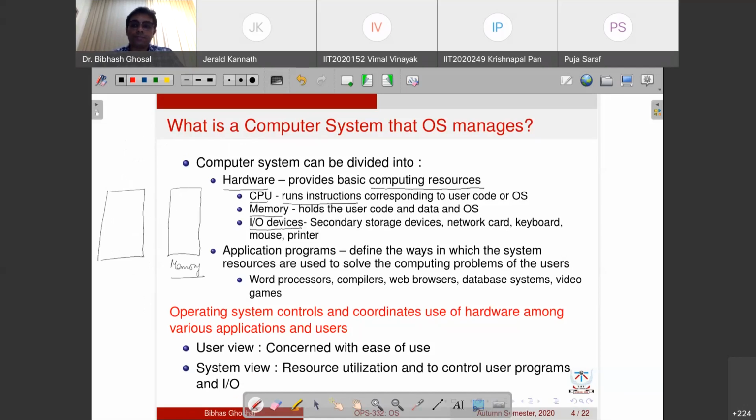in this memory. So this storage location called memory will have these instructions one by one. Instruction number 1, 2, 3, 4 in this way. So these will be the instructions that are given or stored, and the CPU will be asked to get them one by one, fetch them and execute, and if required, write something. So we call this mechanism of executing things a fetch-execute cycle.